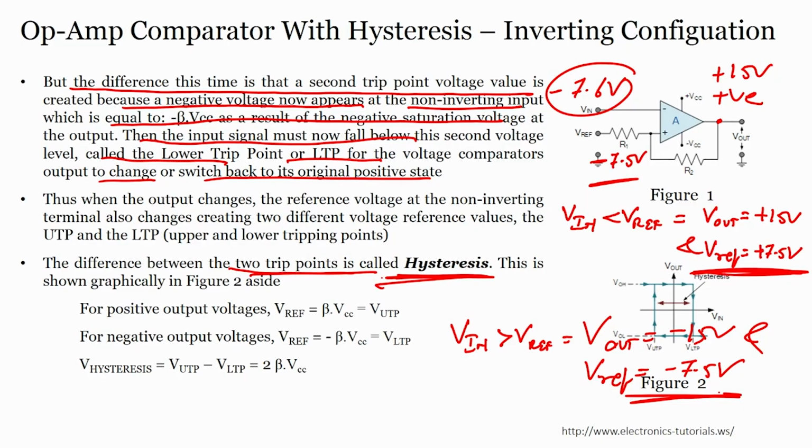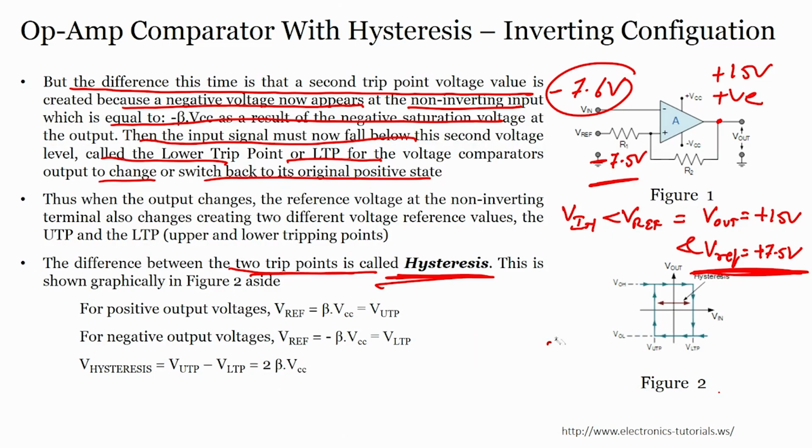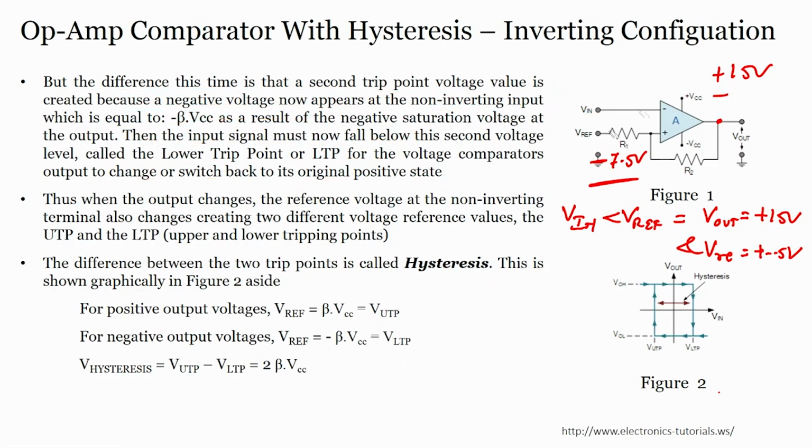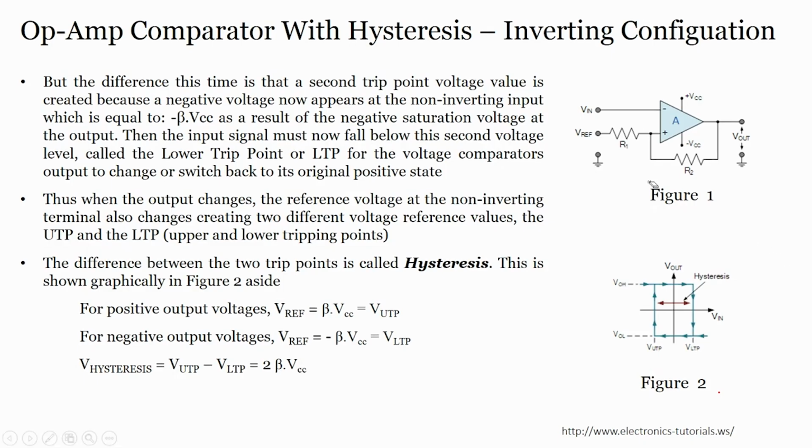So, what is hysteresis? You can design it so that the difference between the upper trip point and the lower trip point, in this particular case, is called hysteresis. Here you see this one, this is your hysteresis. Okay. Very easy, extremely easy, super easy. Now, everything becomes super easy because you already know how to use the operational amplifier in various applications, right. So, when I talk about comparator, immediately your brain works that yes, comparator, very easy: inverting higher than non-inverting, output is negative saturation; non-inverting higher than inverting, output is positive saturation. R1 and R2 are there, what else, the divider, R2 by R1 plus R2 or R1 divided by R1 plus R2, right. If R1 equals R2, it is half times V out, so easy.